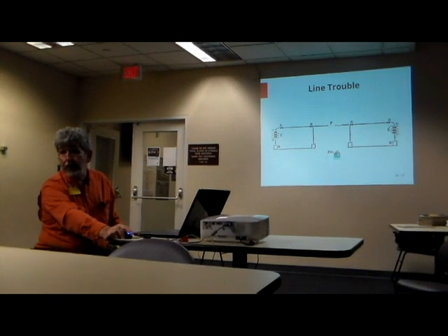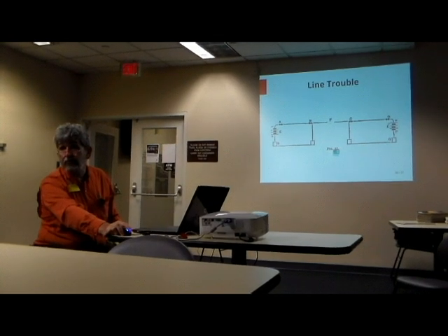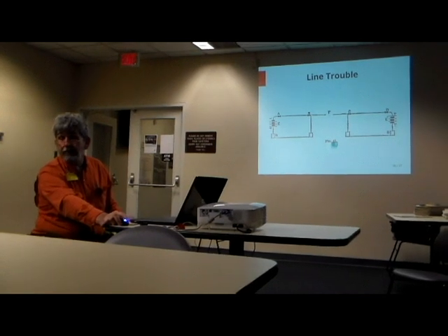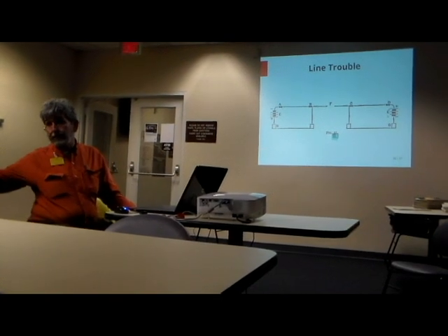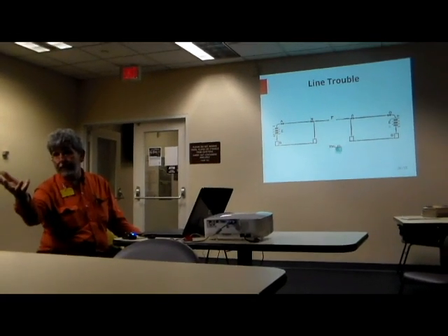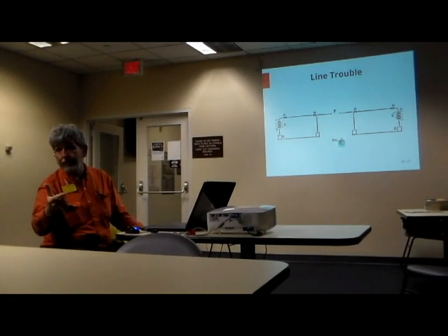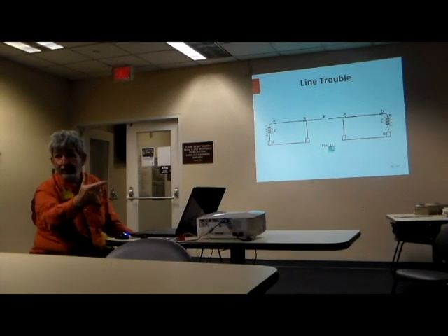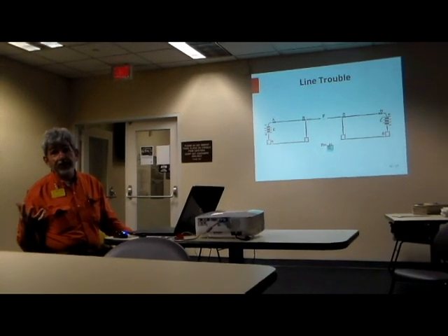So what happens when the line breaks is every telegrapher had the duty to connect two sets of receiving instruments: a second relay, if he or she had one, or a line sounder, if that was the remedy, between each side of the line and earth. Then the terminus stations begin it themselves and call the next station, and when he gets the terminus station signal, he normalizes his line. If it holds to the next station when he normalizes it, if the sounder stays pulled in, the wire's good to the next station, they signal him, they call the next station after he normalizes. If they reach her, they call the next station until finally a station doesn't answer.